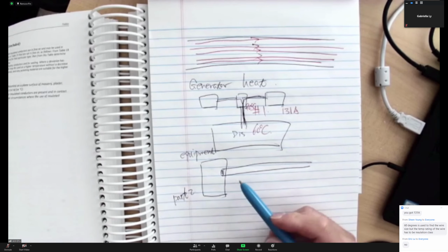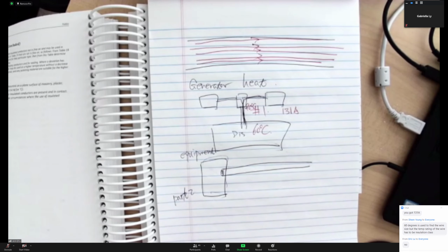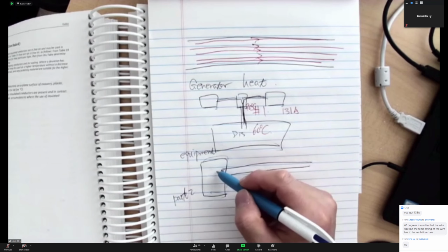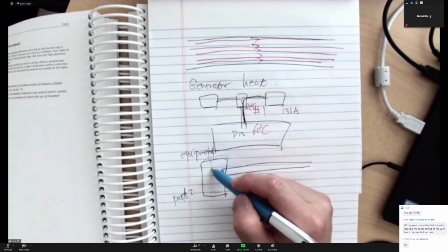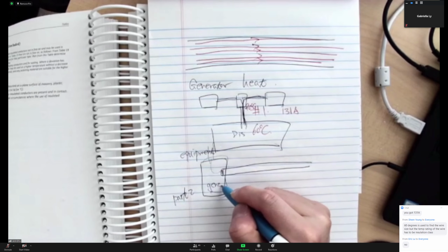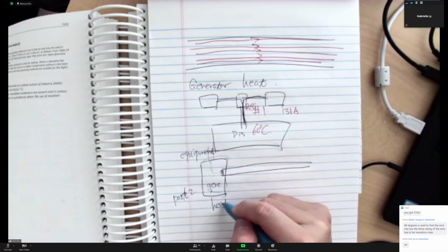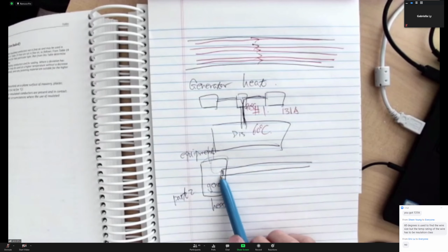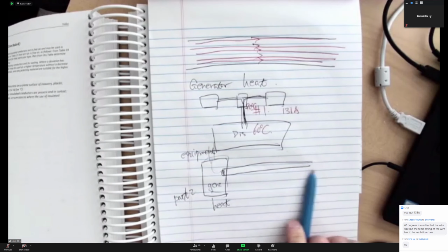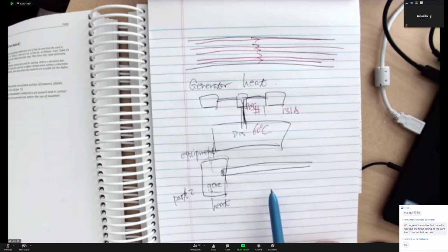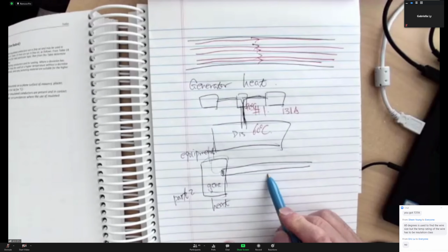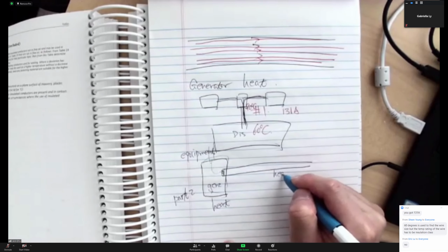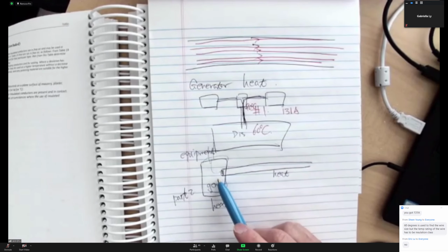So what they try to do is, because equipment usually has a cabinet, doors, locked enclosures, they carry electrical current or whatever, and they're going to generate heat. They will have heat build up in there. They try to use our conductor to carry the heat away. But we as electricians pick a conductor to carry the current. We also generate heat. We try to bring the heat into the equipment. That's where the conflict starts.